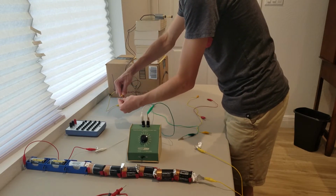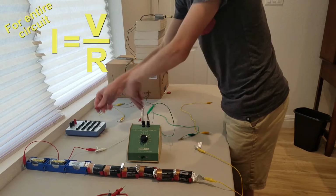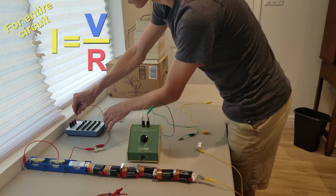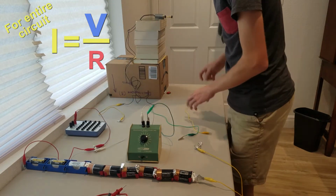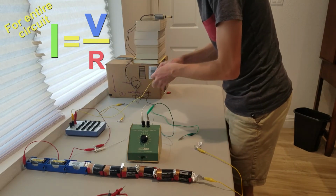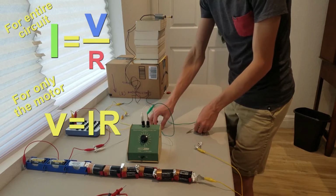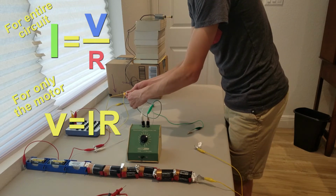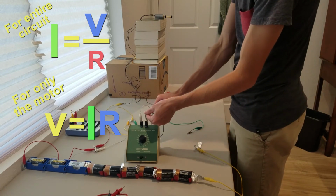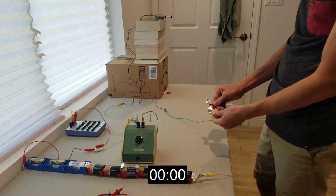Looking at the whole circuit, using a variant of Ohm's law, current equals voltage over resistance. The voltage of the circuit remains constant while the resistance decreases. Since resistance is in the denominator, when it decreases, current will increase in the circuit. Now looking at the motor, using the previous version of Ohm's law, voltage equals current times resistance. The motor's resistance is constant, but the current is increasing, meaning that the voltage drop across the motor must also increase, therefore decreasing the time interval and giving us our final answer.